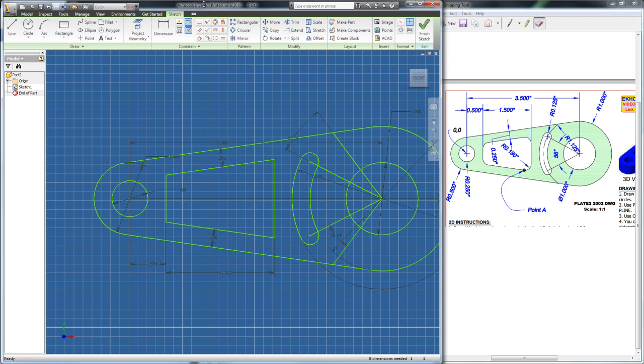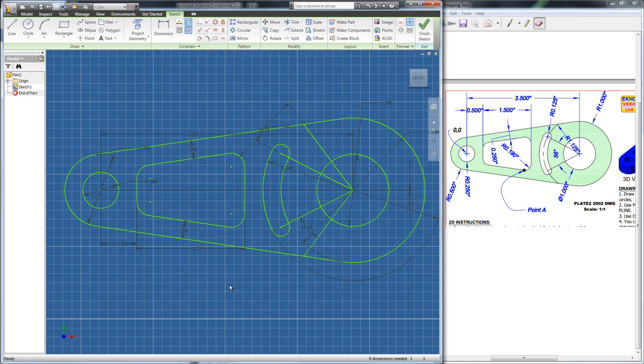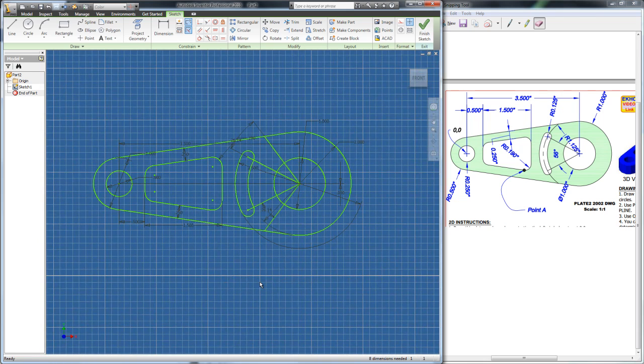Okay, we need fillets. You know that tool, fillet tool. What's the radius? The radius of the fillet is 1.9 specified there, so let's hit up some fillets. Escape, and there you have it. We got our sketch. 2D sketch. It doesn't look elegant. The dimensions are all over the place, but that's a sketch. This is not the same thing as AutoCAD. This isn't our final product. This will be turned into a part in the future.